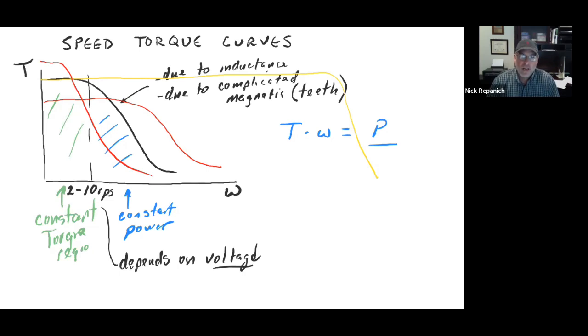The difference is inductance, and an inductor takes time to charge. So when you hit it with current, you have that rise time of the inductor. At some point, let's say when you get to 10 revs per second, right here at 10, over here might be the changing speed at 20 revs per second, meaning you have less time between winding changes.